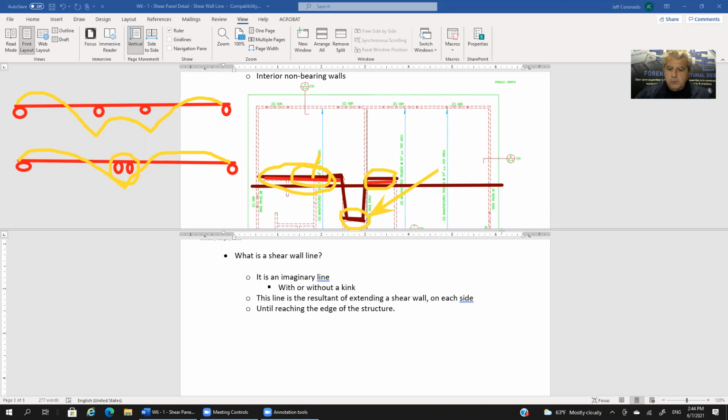Okay, so this one here, let me use even another color. How about if I use green? This condition mimics more having two closely spaced but separate supports. So you would have to take that into account. They cannot be considered part of the same shear wall line.